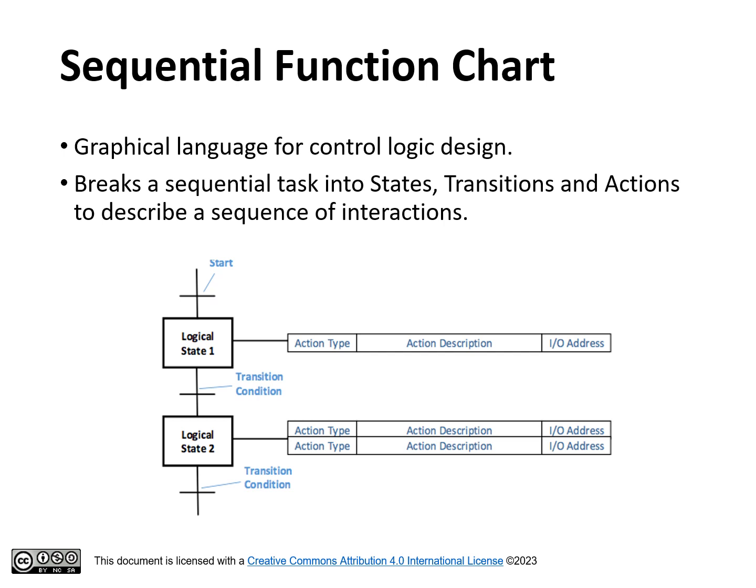A sequential function chart, SFC, is another graphical tool for control logic design. It breaks a sequential task down into states, transitions, and actions that are graphically depicted to describe a sequence of interactions. The sequence of interaction flows from top to bottom as shown in the figure.